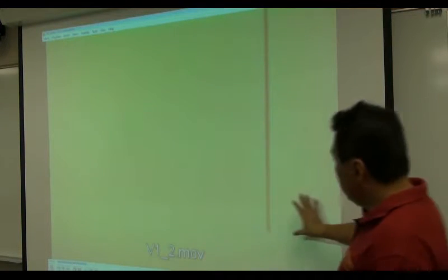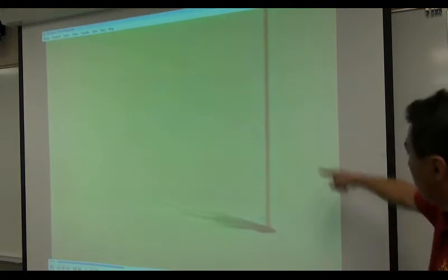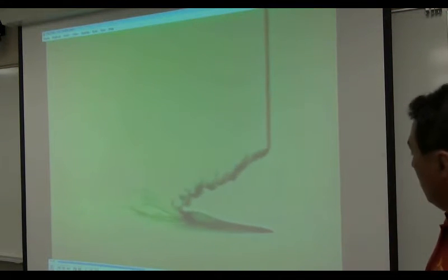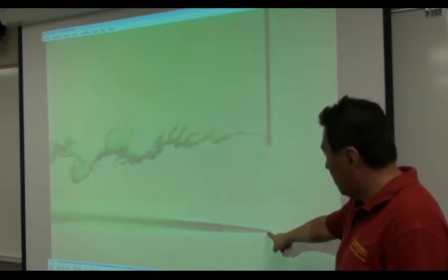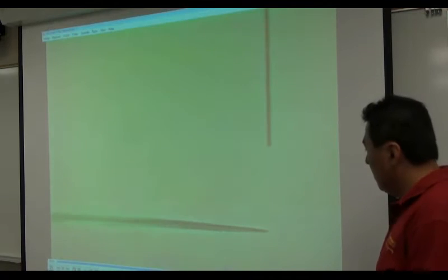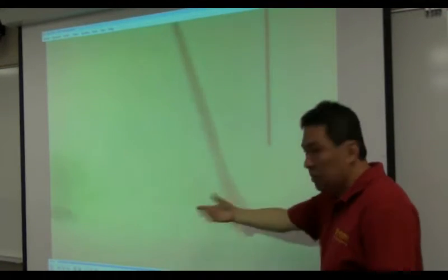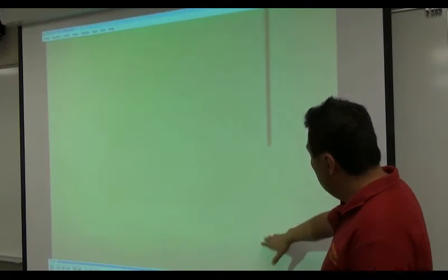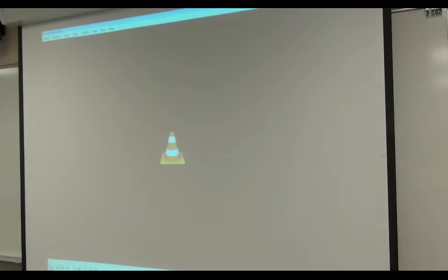This is the water flowing from right to left, and this is solid surface. Then you're going to introduce your ink. So as you can see on the solid surface, ink sticks on the surface. It doesn't flow, just like other flow field. In order to make this ink flow, you need to literally move from the surface. In other words, on the solid surface, fluid sticks on the surface. This is called no-slip condition.